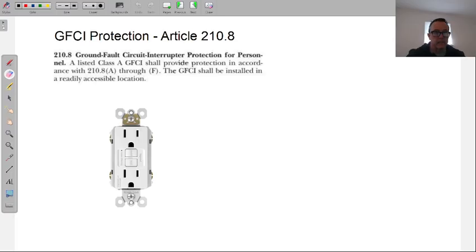So these days, under the sink, GFCI receptacle for the garbage disposal and the dishwasher, as I mentioned. So you'd have to break these two tabs, which GFCIs have that feature as well.